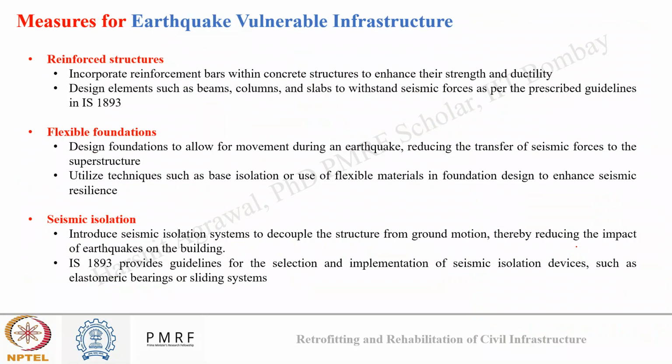So this was all about how, using different means, we can strengthen an existing infrastructure which has already undergone damage or which is very vulnerable to get damaged in the near future. Now suppose we know about the historic condition of a place, and we are constructing a new infrastructure at that place. During design or construction itself, we can take seismic strengthening measures, which will help prevent my structure from undergoing damage. Rather than protection, if we take measures during the design, we will have a preventive technique.